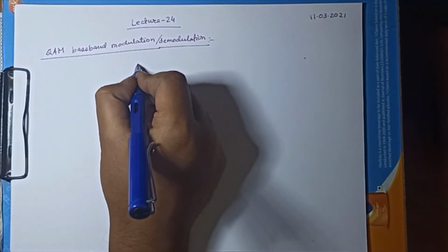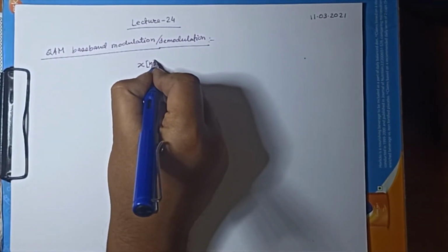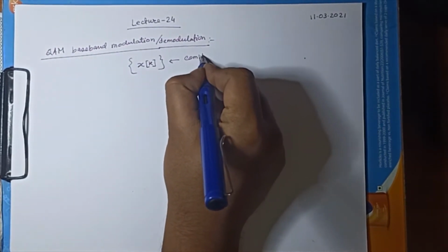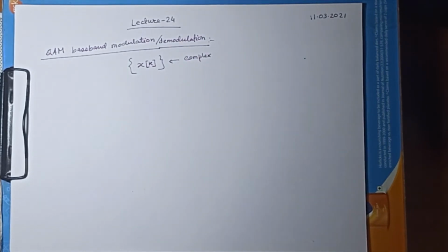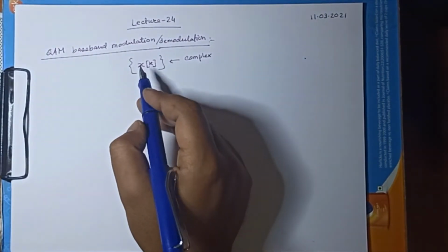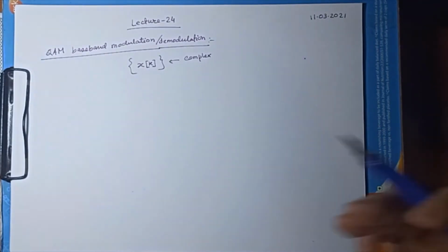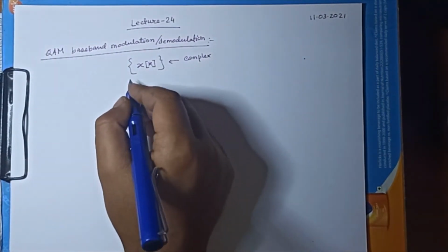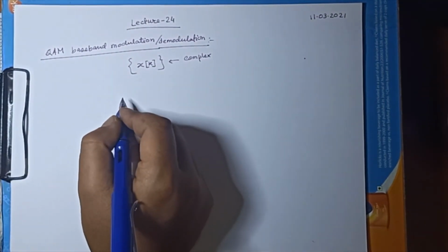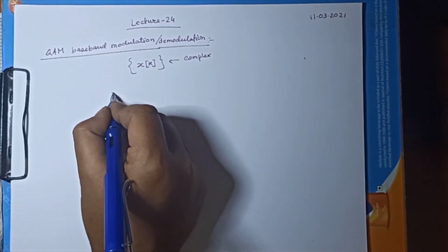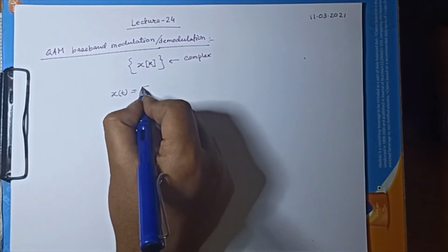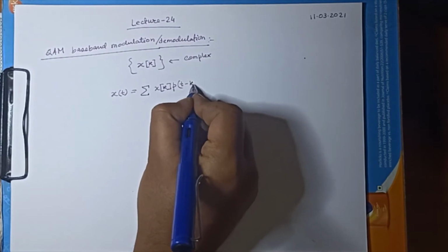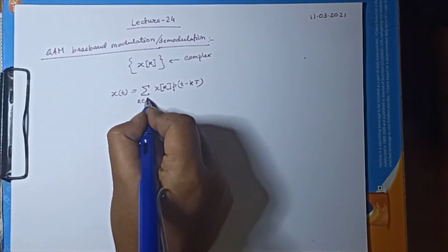So we have the complex signal points. I am writing it as small x, you know why, because although they are random, this is basically what has been coming out. So this is basically one of the sample sequences. This is complex, and we have our modulation filter p in the baseband. So we get our x(t) to be the waveform, summation x_k p(t minus kT) for all k, all integers.